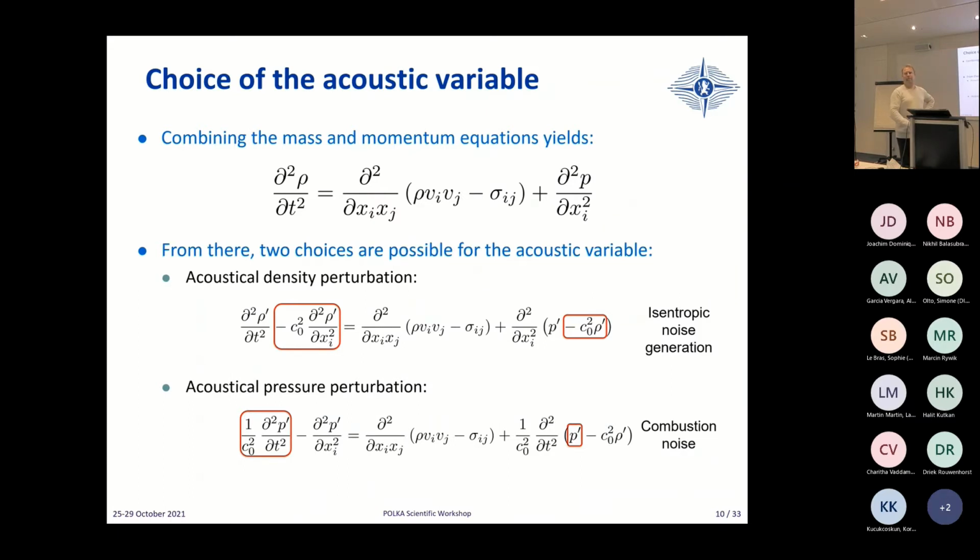And if the entropy fluid, which is a combustion product, has a different gamma, Poisson ratio of the Cp, heat capacity at constant pressure divided by the heat capacity at constant volume, then it will contract a different way than the surrounding fluid, and you have a monopole. So in general, you can have both. In a general sense, you have both, and then depending on the difference of compressibility or not, you might have the monopole or not.